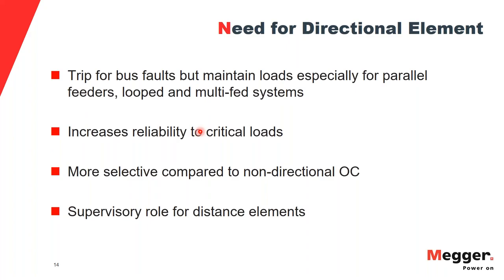And the other thing is, it also acts in a supervisory role for distance elements. Now, we all know that distance elements work on the principle of impedance calculation. So they have forward zones, they have reverse zones. Basically, the distance relay calculates the impedance, sees if the fault is in the forward zone or in the reverse zone, and works on that principle.